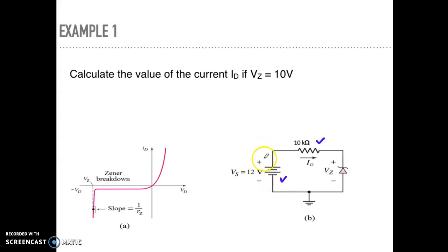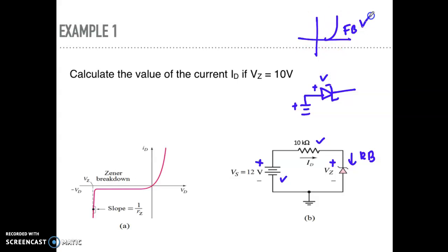In order to do this, here will be connected to plus, and when your Zener diode is connected to plus at this line of the Z here, it means it operates at reverse bias. This is a Zener diode, right? If we have the voltage connected here plus and plus, it will be at forward bias, so it's like a normal diode.